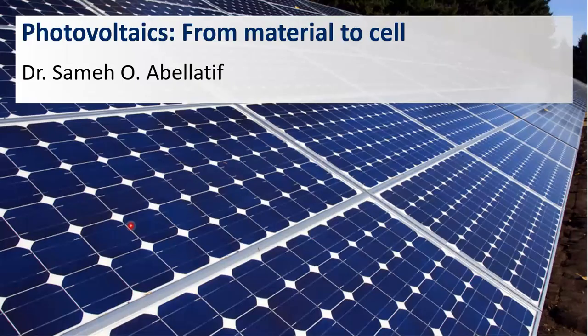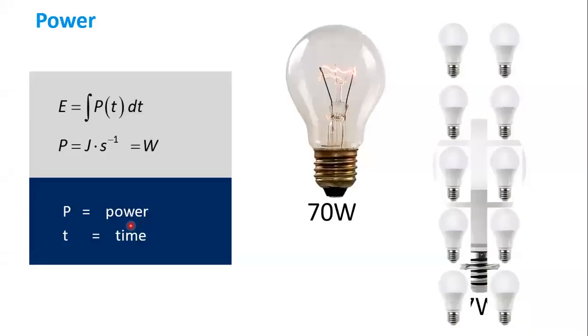However, when we start doing what we call the sizing process, we size energy, not wattage, because it's not the process of the PV wattage. It's a process of how much energy this PV will produce per day, and I am as a customer, how much energy I consume per day.